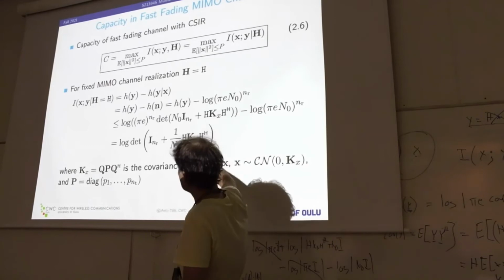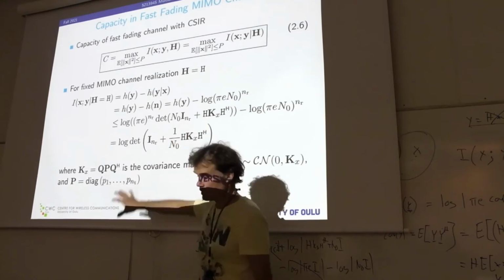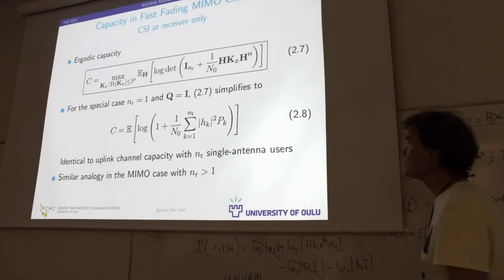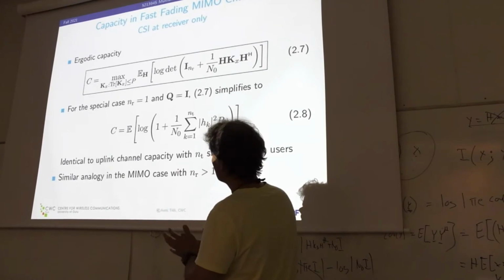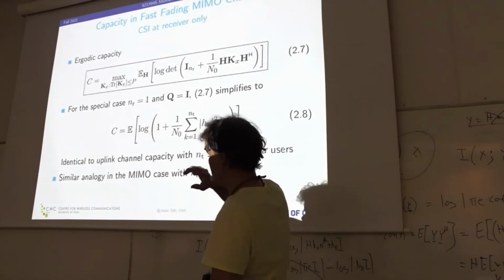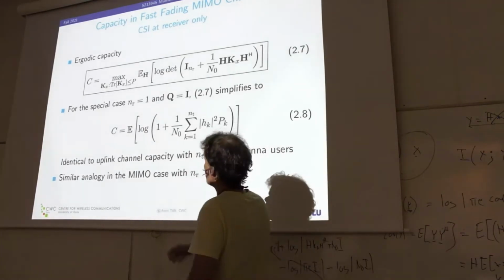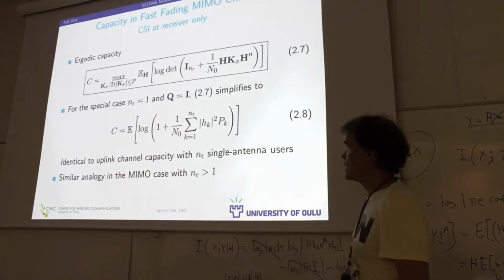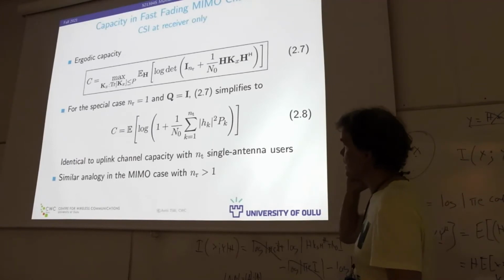Okay, so this expression here was given a certain channel realization. In general, when we have a fading channel, to compute the so-called ergodic capacity we discussed in detail in Wireless Communication 2, we simply need to take an expectation, or an average, over all possible channel realizations. That's clear.